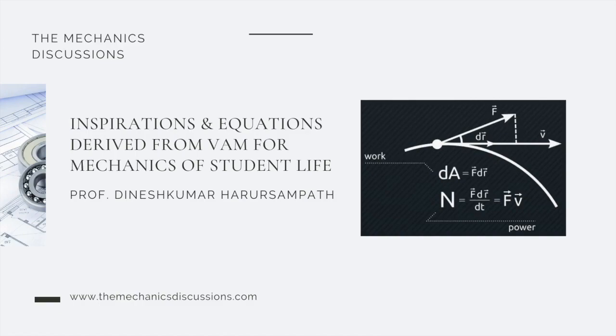So machine learning is going to be very critical in the case of composites, even in healthy structures, but even more so in the case of damaged structures, where you try to learn about the mechanics of the damage involved, be it fiber breakage, fiber-matrix debonding, delaminations, or matrix cracking, or combinations of these, and how they affect the response of the system, and how you can learn from that to predict in a completely different scenario that you don't have as part of your data for the machine learning, and how you translate that data to understand the future.